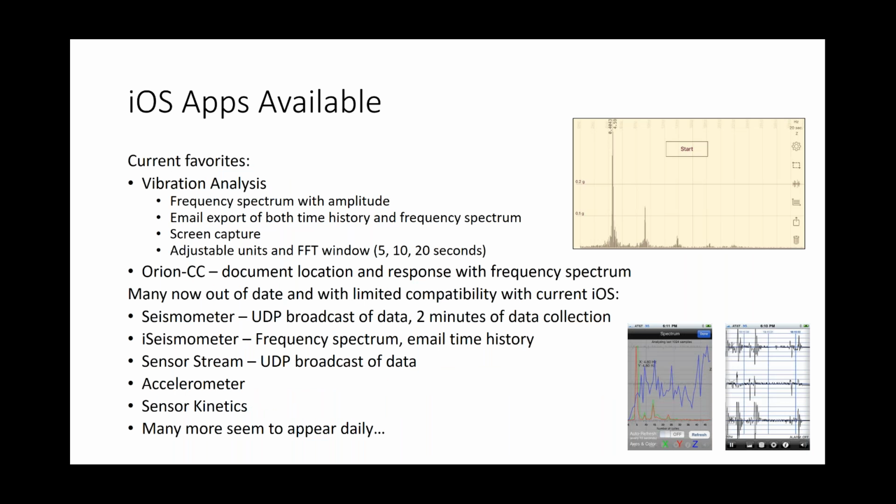I said I would talk a little bit more about the apps that are available. My current favorite is one called Vibration Analysis. It's on the Apple App Store. The nice thing about it is that it generates a frequency spectrum that includes the amplitude and the frequency at the peak. So you get very clear results immediately.